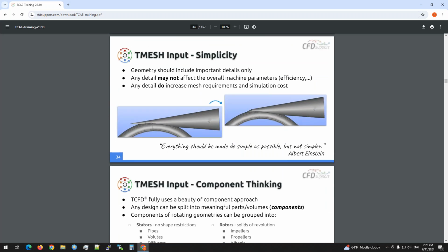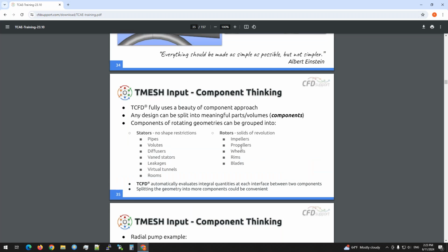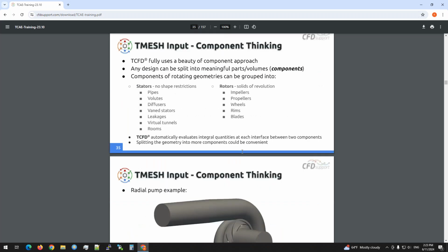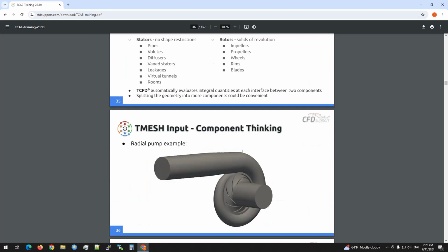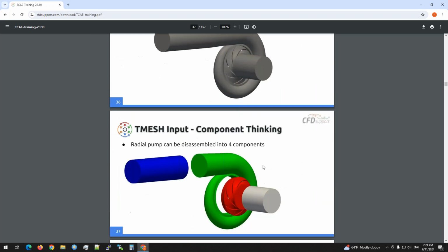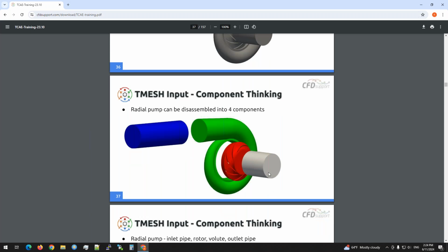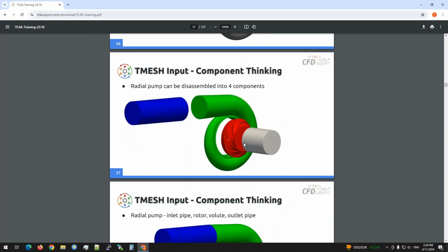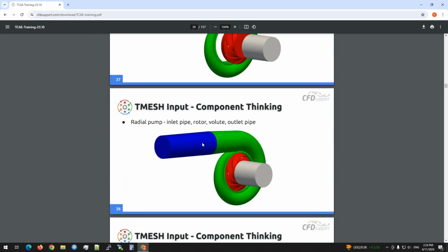And this is the first part, to create the flow domain. So this I think is pretty clear. The second option is to tailor the flow domain, and then afterwards export the STLs towards the proper requirements and inputs, which then leads to a nice setup for the CFD simulation. So here, because we are speaking about rotating geometries, we need to split the flow domain into components, we call it, and the components can be distinguished as the rotating one and a stationary one. So the splitting has to be done typically in the CAD by creating other surfaces, which are called interfaces, which define the interface between stationary and rotating part, or in general between two adjacent components.